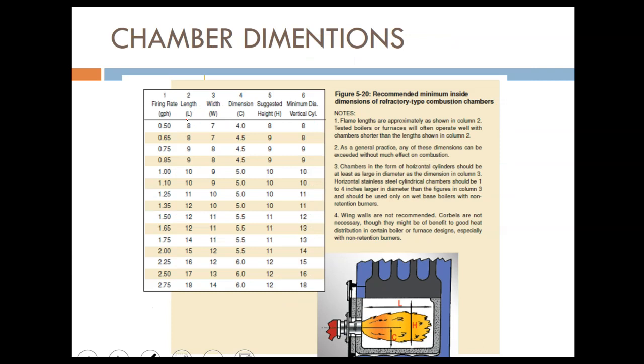Again, more about the dimensions and the location, and where you center the burner inside the boiler. So these are the locations of the center of the burner, based on the size of the chamber. And if you notice, you don't want the flame to be hitting the floor or the top heat exchanger or the sides. If it does and you did not pay attention to it, this can cause one of those areas to overheat, and eventually the boiler will crack.